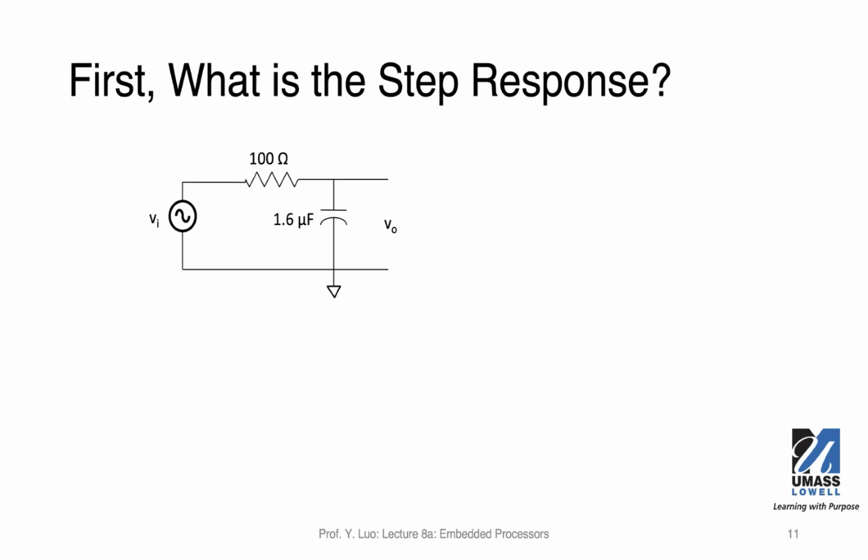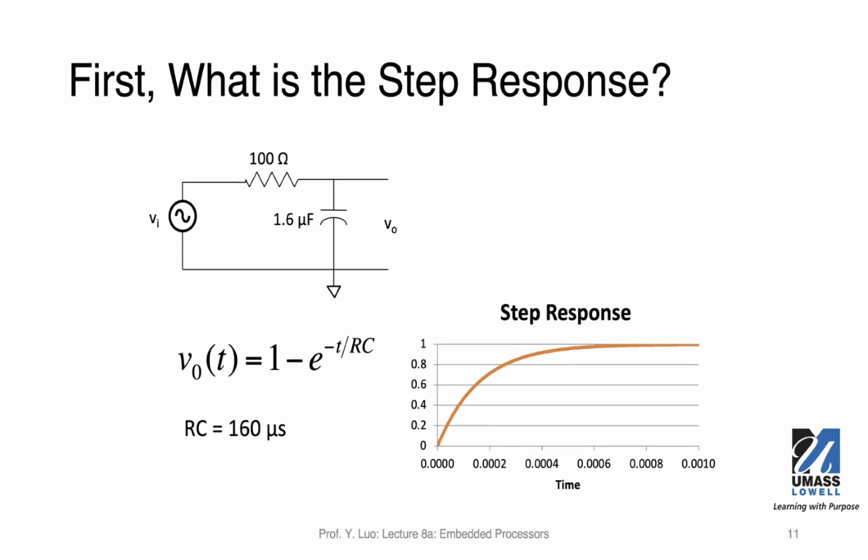Now, one thing we want to show is the step response. The step response is essentially when you have a voltage of 0 as an input, and momentarily you change that to a voltage of VDD. So how will the output respond? As you know, when we have such a sudden change, the capacitor will go through a very dynamic process.